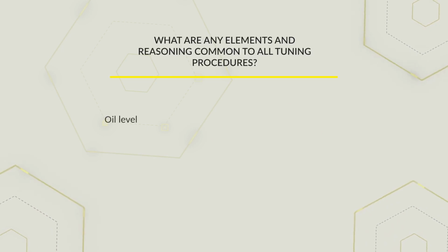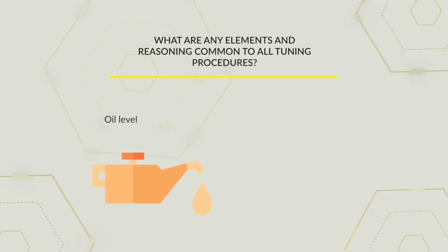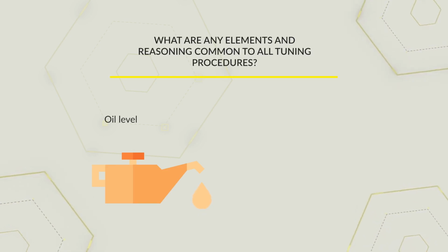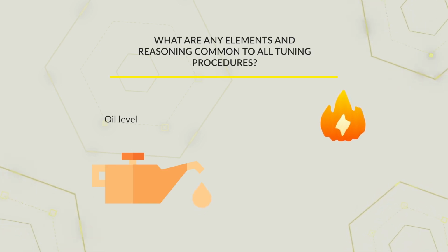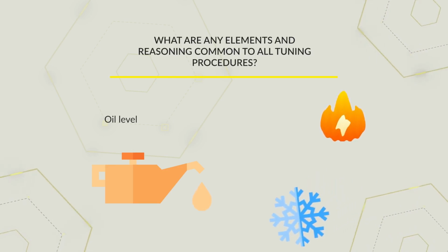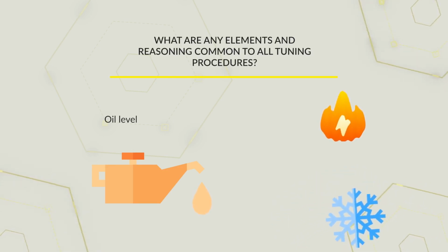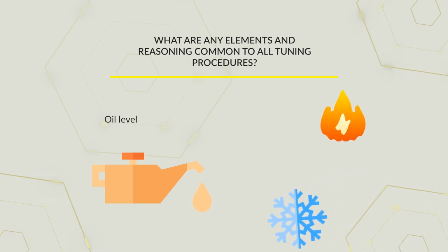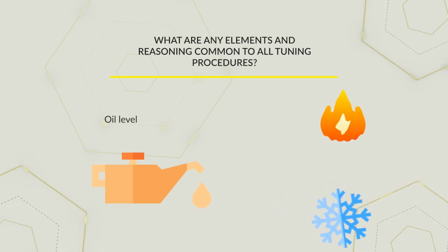Oil level. If the level is above its maximum, first check the engine coolant temperature. Then, if the engine is hot, check the level again when the engine is cold. Under certain conditions, excess oil can affect the calculation of engine torque loss, thus resulting in inconsistent performance.